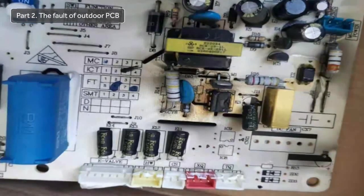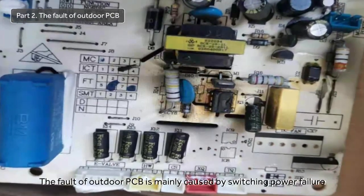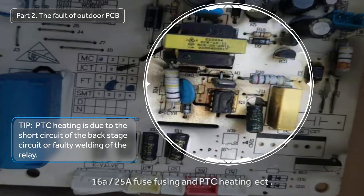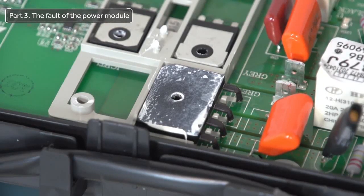Part 2. The fault of outdoor PCB. The fault of outdoor PCB is mainly caused by switching power failure, 16 amp, 25 amp fuse fusing, and PTC heating, etc. Part 3. The fault of the power module.